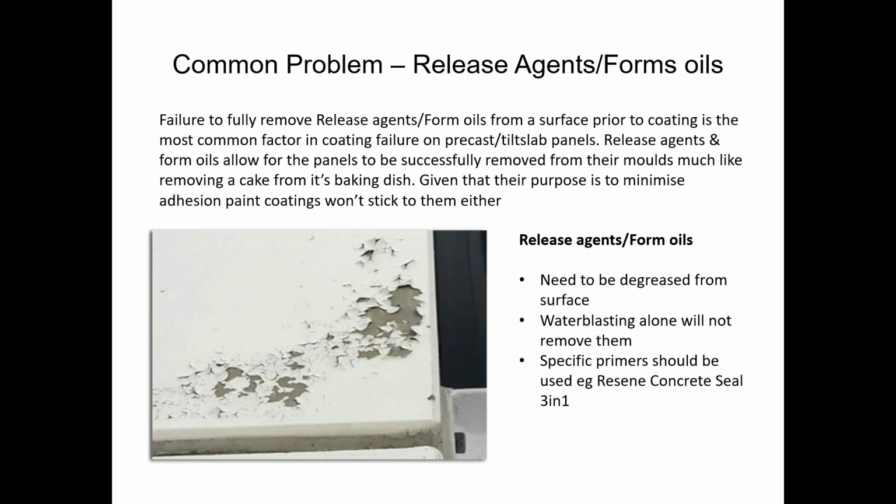But now we've got some release agents on the concrete. So if you do paint it, we need to make sure we remove those. There are so many different types of release agents these days that you need the concrete people to tell the paint people how to remove it, because some of them just wear away, some need to alkali cleanse, some need to be solvent washed. So the concrete people need to be able to advise you, and then you tell us what type is there, so we know how to clean it to make sure we can remove it, or the paint can actually come off.